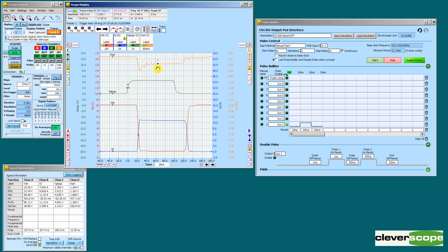So we can see the change in voltage, and it's about 7 millivolts. I'm guessing that corresponds to the 100 milliamp change we saw. We could work it out based on the RDS on of the FET.